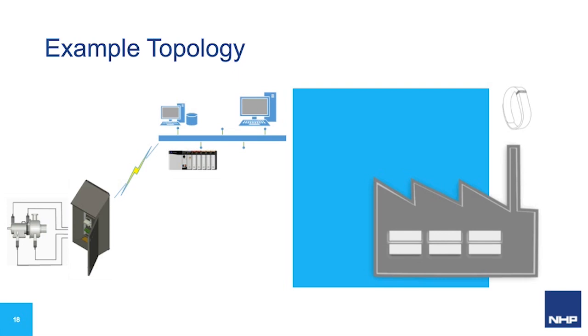You can either get someone to get your existing baseline values, that's fine. The advantage of using NHP is you can give us an order number that we can get you a field service engineer through Rockwell, and that will actually get presented to you in the required add-on profile friendly format. So think of getting the report back. These reports are usually extensive. They have all the spectrum readings, but at the end of the day, all that's important for you is to be able to say to your control systems engineer who's setting this up in the PLC, I need these values set up. So we'll provide you with an add-on profile friendly format that you can simply set up those values. And then once you've done that, you're on your way.